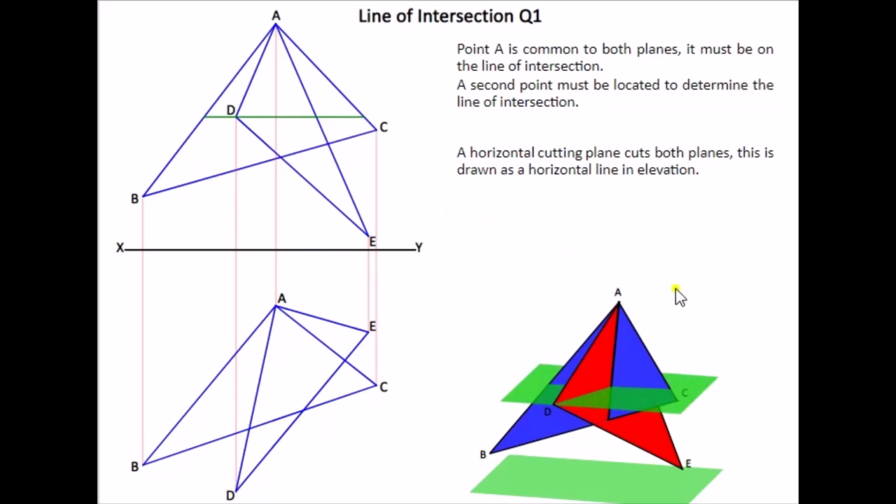So in the 3D graphic, this shows what's happening. We're cutting through the two lamina surfaces, and as you can see, when you cut through the two lamina surfaces, it's also cutting through this line here, this line of intersection between the two laminas. So this here is the point that we're trying to find.